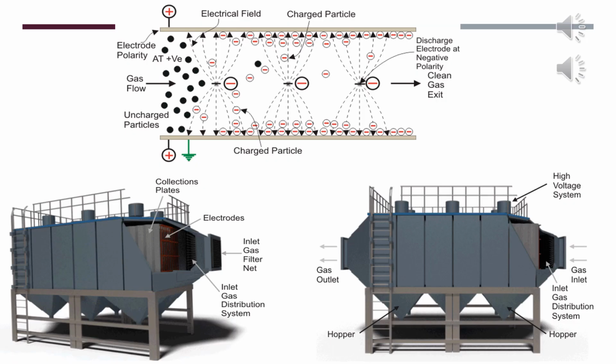The medium between the electrodes is air, and due to the high negativity of negative electrodes, there may be a corona discharge surrounding the negative electrode rods or wire mesh. Corona discharge is actually an electrical discharge brought by the ionization of a fluid, for example air. The air molecules in the field between the electrodes become ionized, and hence there will be plenty of free electrons and ions in the space now. The entire system is enclosed by a metallic container on which one side is provided with an inlet of the flue gases and the opposite side is provided with the outlet of the filtered gases.